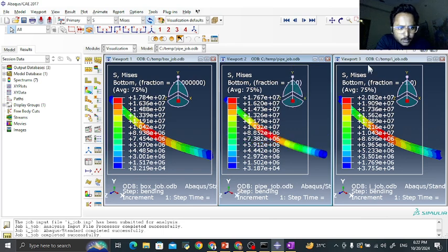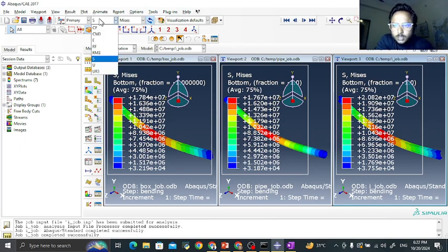And here select I, it was already selected, and deformed is also already there. So you can take the screenshot of this page, and in a similar way you can go for U also. This is for the stresses, and if you switch here to U, meaning deflection, you can show it.